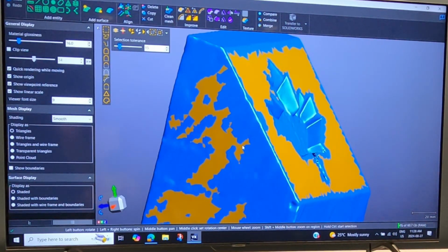So perpendicular. Yeah, perpendicular. Each one of these is pointing the way the pen is. But if I go over here, whoop, the normal veers off. So I'm not going to pick that. The selection tool is going to stop here and not go around. Very useful when we're creating planes, to pick those nice flat surfaces.